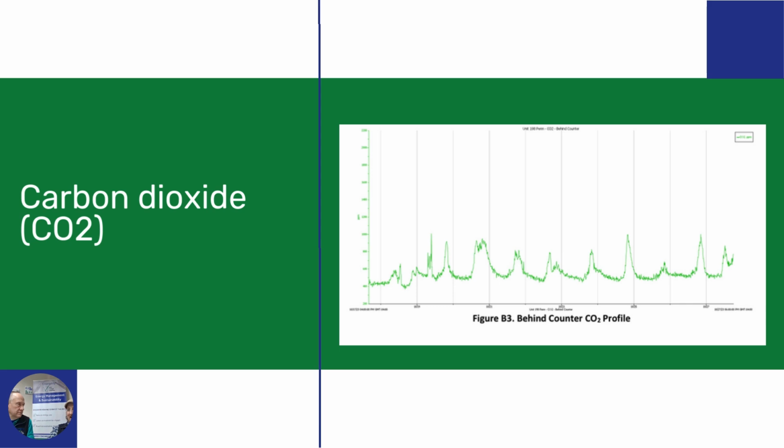And if it is occupied, does that line up with how the outside air system is operating for the building? And should it be putting more outside air in, or is it pretty flat? And also, we know that the space was occupied and it's just dumping 100% outside air in to compensate for the people in there, but it's also probably costing them a fortune to run that system if it's giving 100% ventilation all the time.